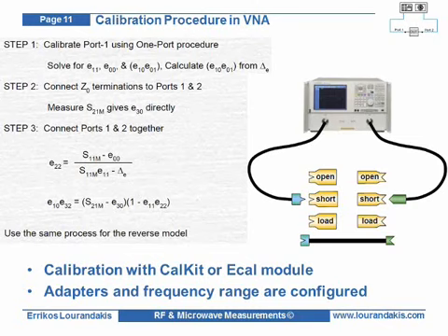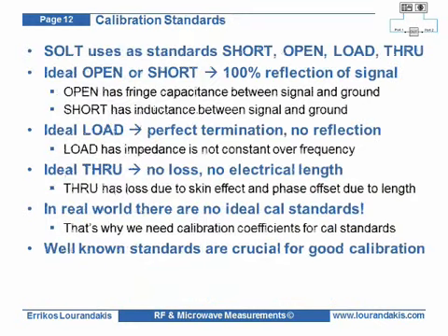After the applied corrections, the reference plane of the test system has been moved to the center pin at the end of the coaxial cable. At this point, we are ready to insert the DUT and perform the actual measurement. As we have seen so far, calibration standards play a crucial role in network analyzer measurements. A widely used calibration routine is called SOLT and has its name from the used standards short, open, load, through.